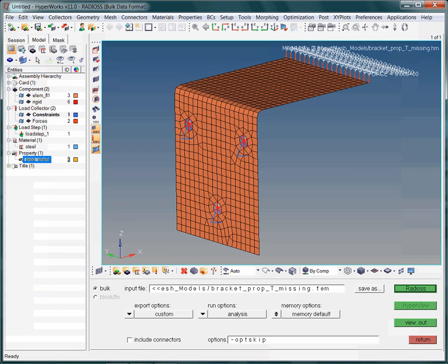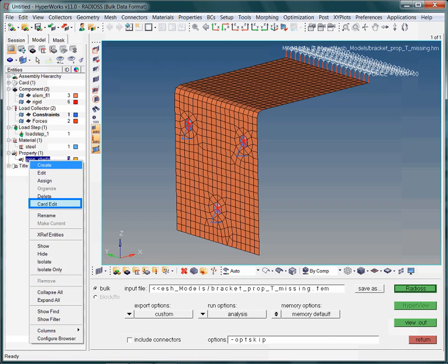The thickness definition is part of the property definition. Hence, let us check the property collector next. Here we see the cause of our error message. The thickness is not specified. Based on this finding, the next step should be straightforward, just assign a value and you are done.